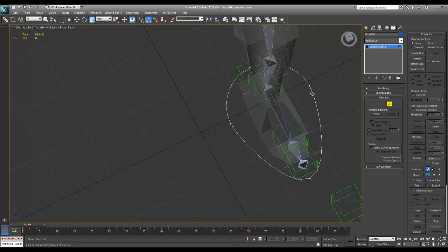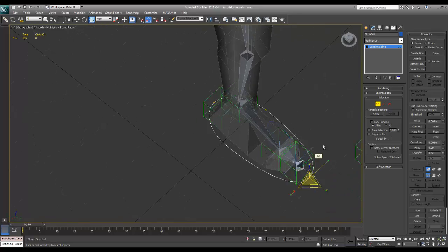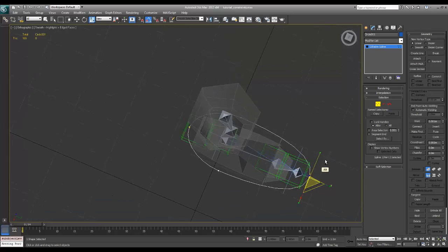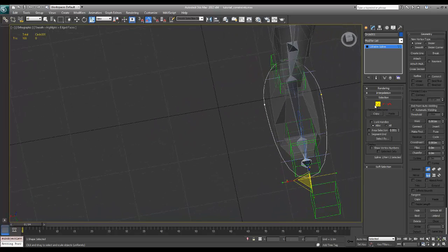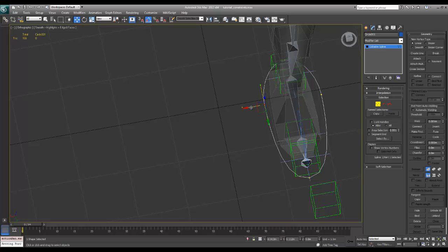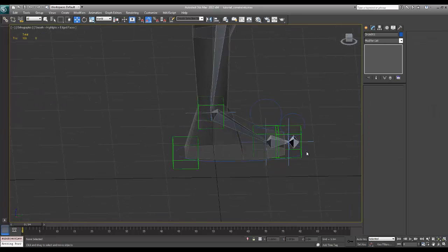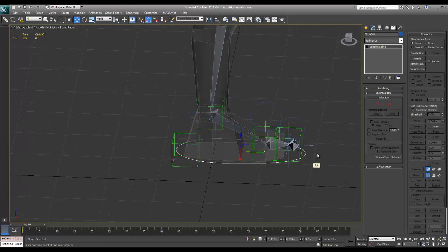Let's select the spline itself, scale it in a bit, select the vertex on the end, and just make a shape. And this is purely aesthetic. It can be whatever shape you'd like it to be. If you want to follow a foot pattern, if you want to push that guy in, make it look more like a foot, you can make it look like a clown shoe. Who cares? It is totally up to you. So at that point, that's going to actually control the foot.